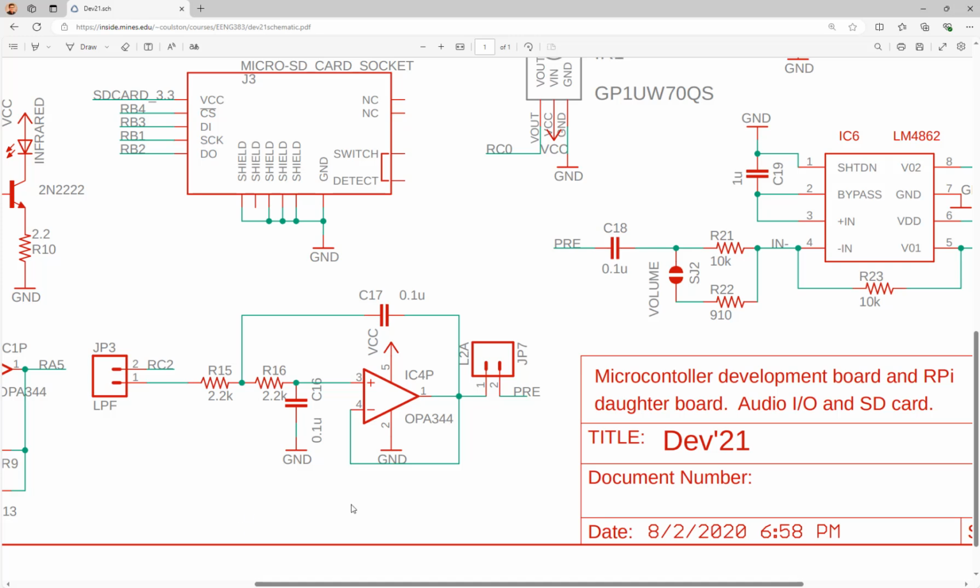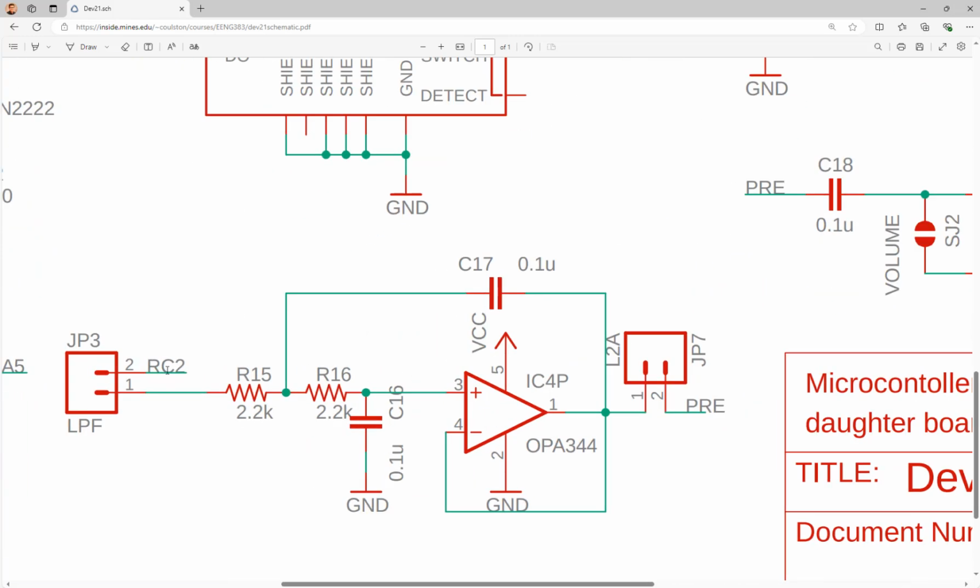So what you can do is, I'll let you guys tell me. If I do not want to use the LPF, I can see the label here is probably, I don't know if this is still a current label for the new PCB. Anyway, doesn't matter. You know that this pin, the other side of the header, is connected to RC2. We're not using RC2. We're using RB5. Keep in mind, RB5 is the output.